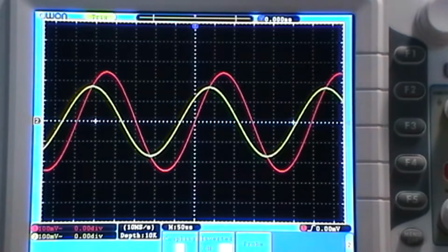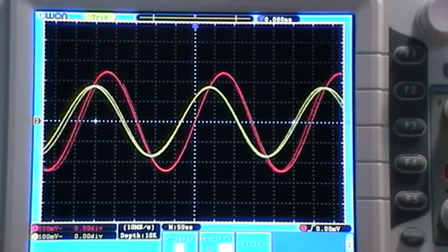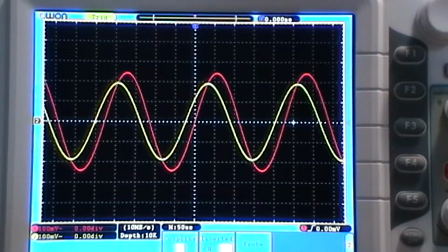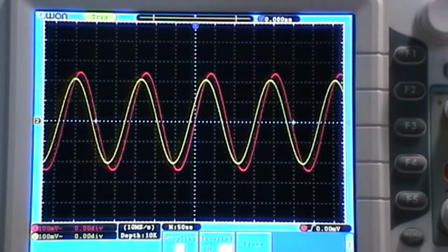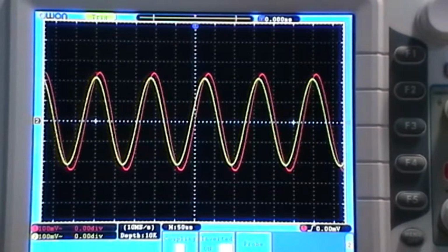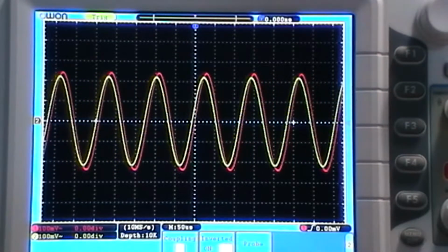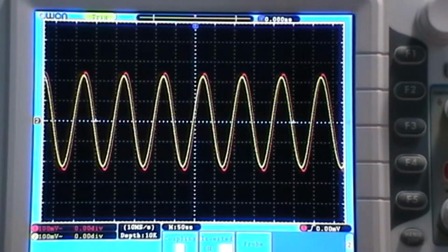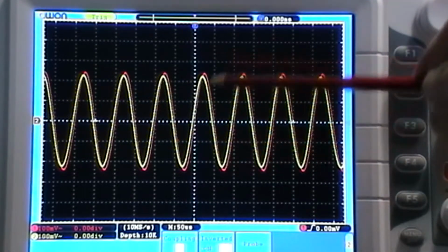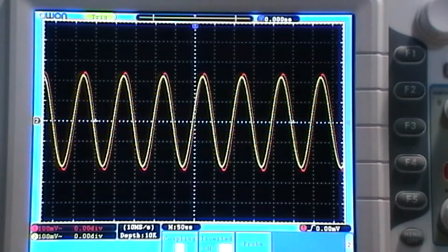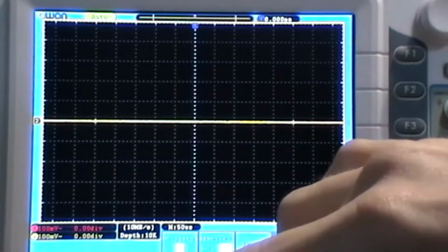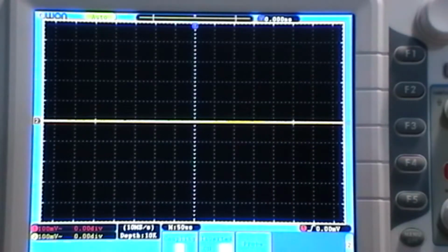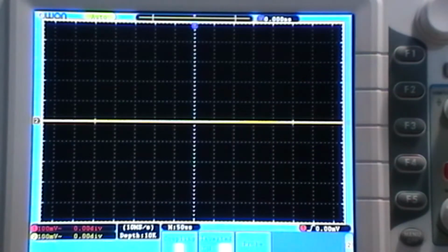And if we now crank this up in frequency, we will get more of that frequency coming through. We've got 7, 8, 9, and now we're at 10 kilohertz, and at 10 kilohertz you can see we've got most of that signal coming through. So let's turn off that channel, signal, and swap it out for the last capacitor, which is my 15 nanofarad capacitor.